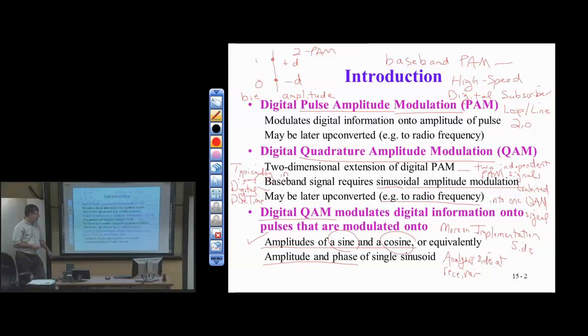But for QAM, we're going to see pretty quickly that you're very sensitive to phase. Your PLL has to be much more precise in QAM. We'll see this in the constellations. So we're not going to use the second view very much, except to realize that we're more sensitive to phase for our purposes in this class. In a digital communication theory course, you would probably go into more detail in the second view of it.